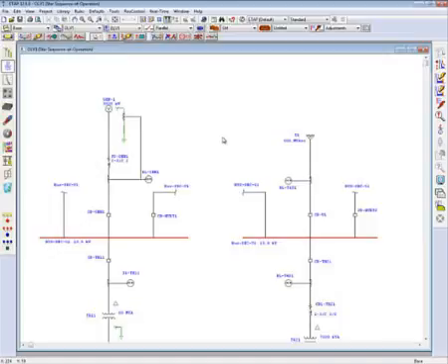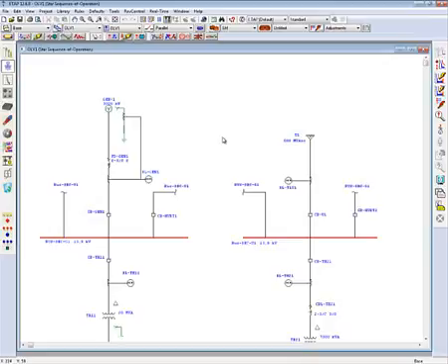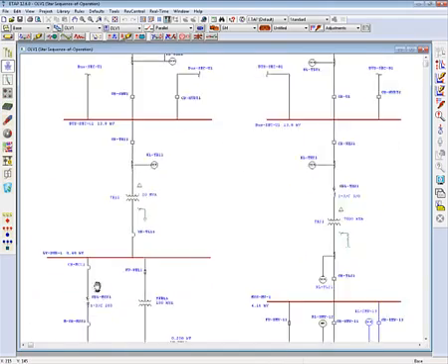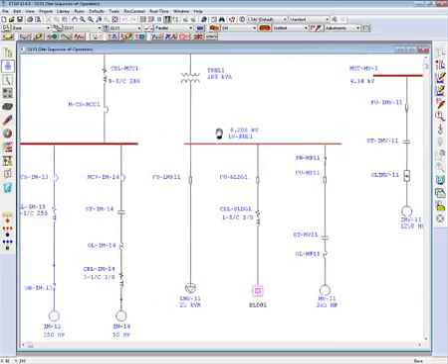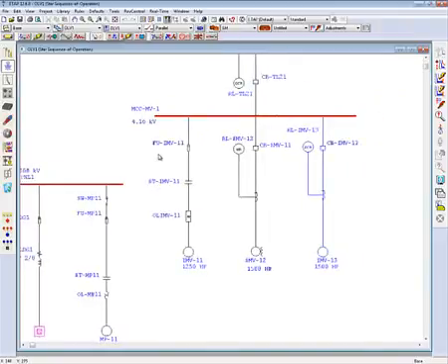Everyone, let me take you to one of the sample projects which I'm going to use for ETAP star mode. I have a system here with multiple sources of contribution. I have a local generator supplying power and a utility which are feeding multiple motors. So we have some low voltage motors rated at 480 volt or 208 volt and some medium voltage motors rated at 4.16 kV.